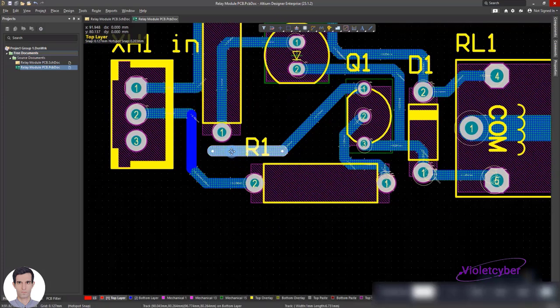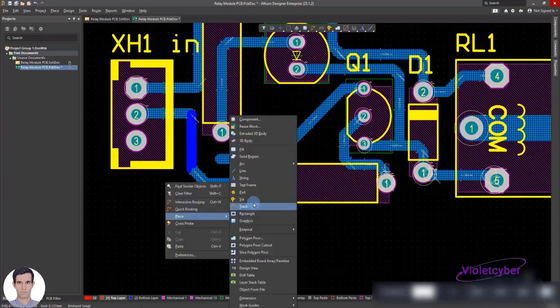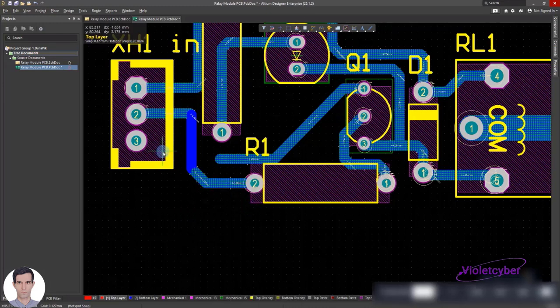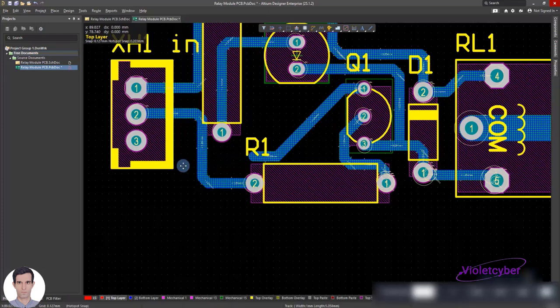So instead of using vias, I'm going to consider a jumper in this circuit. And for this circuit, what is the jumper going to be like? I'm going to go here. We select the track again. So how do we put the jumper? We'll move the footprint back a little bit, so we'll change this footprint too. We'll put it here, and then we'll come here.